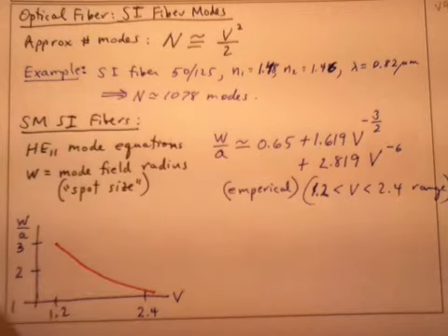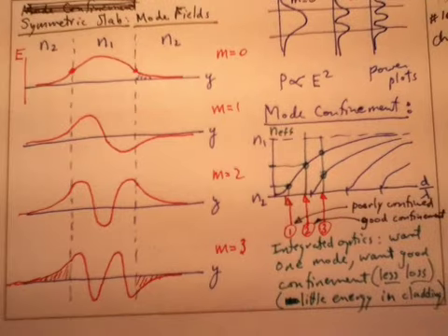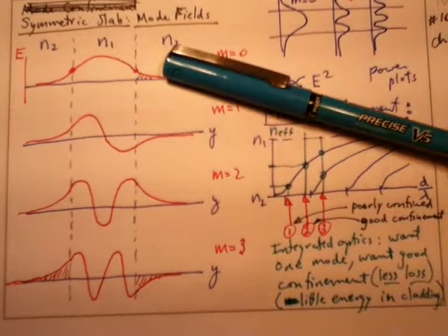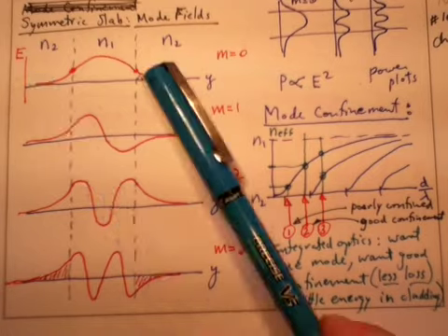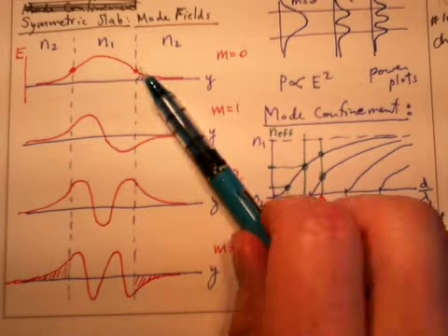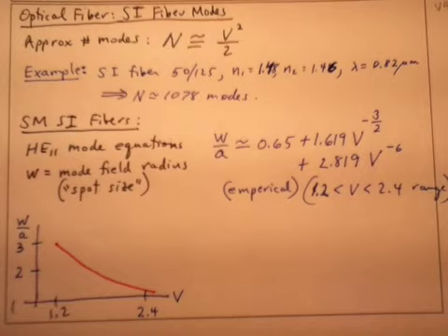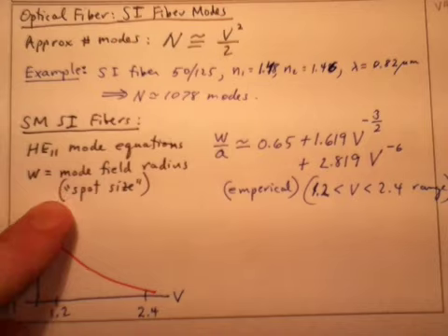And we're using a Gaussian beam approximation to the lowest order mode because it really does work. If you'll recall our slide from Chapter 4, where we looked at the modes of the symmetric slab, the lowest order mode did have an approximate Gaussian profile here. Okay, so the lowest order mode of the slab has an approximate Gaussian profile, and likewise the lowest order mode for the optical fiber also has an approximate Gaussian profile. So that W parameter, the mode field radius, or the spot size, is of great interest.